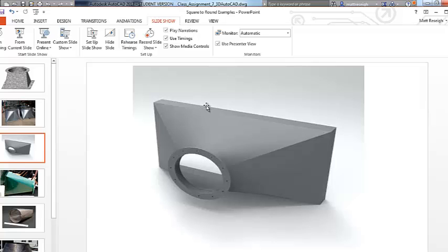And I like that this one shows the pan side. Where the rectangular pan goes up, they just added a straight section on there. We can actually develop the squared around section and then just add on some bent straight sides. So those can be add-on items. Same with the collar, same with this transition to make this into a pan. That can all be added on after I've done the squared around development, given my purpose. So I like that this shows this.